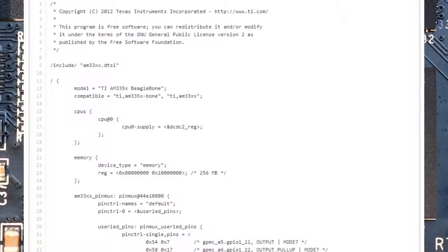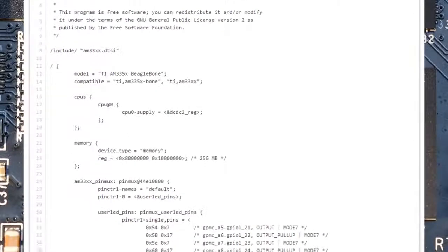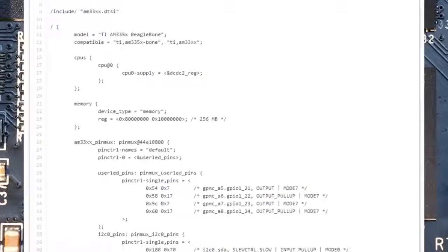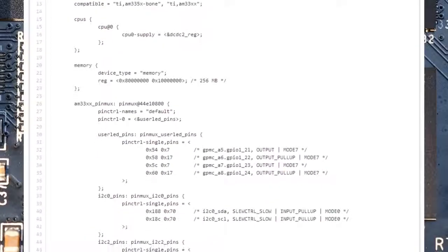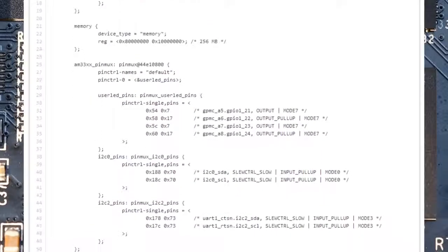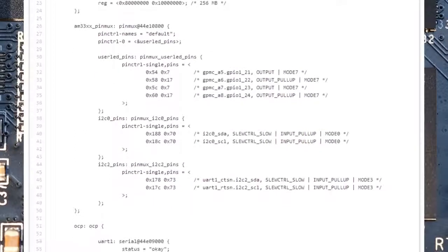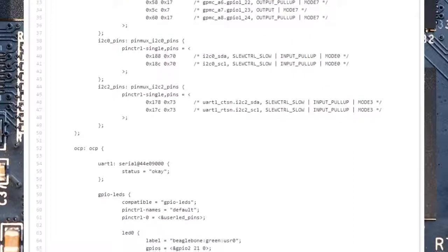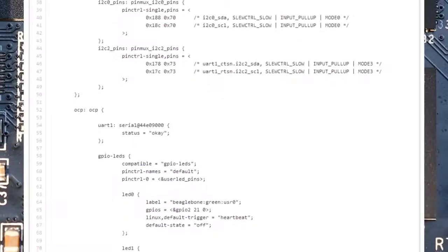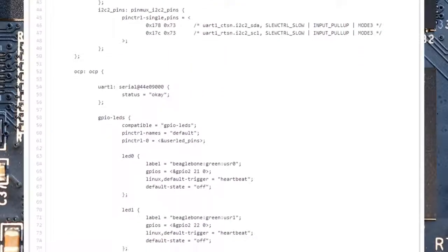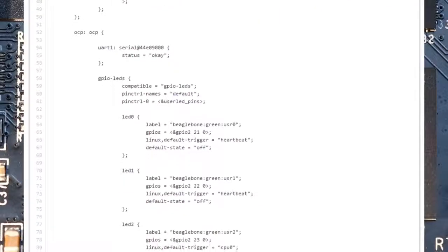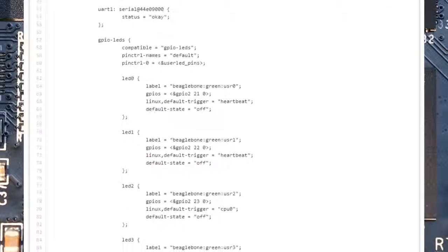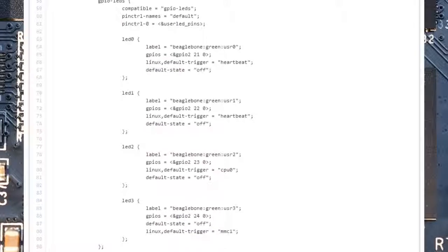We have tools on our Beaglebone already to support us, such as a device tree compiler, which we call DTC, that converts between human readable and editable device tree source, which is .dts format, and the compact device tree blob, DTB representation, which is usable by the kernel. See scripts/dtc in the kernel source directory for details on the tools.